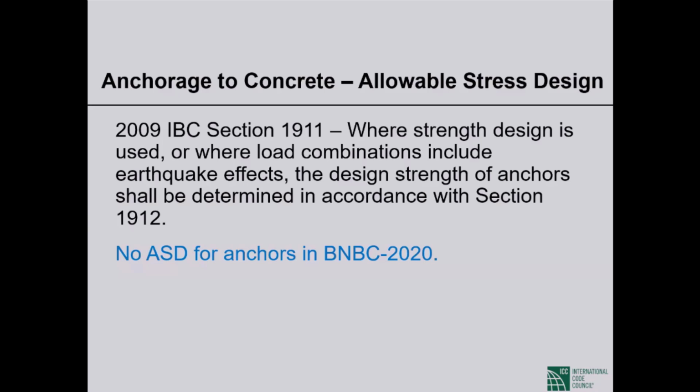Now, I wrote in blue letters, and whenever you see blue on the slides, it relates to BNBC 2020, that there is no allowable stress design of anchors in BNBC 2020. All you have is strength design of anchors in Appendix K, as in king.